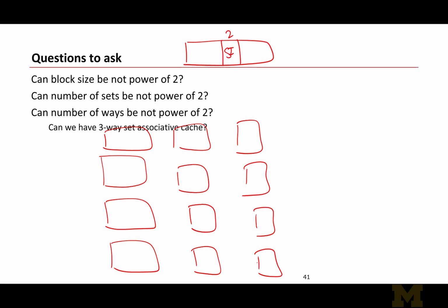So it is possible to define set associativity to be not a power of 2, as it doesn't really impact the way that we would configure the caches in terms of utilizing the number of bits and so forth. But oftentimes cache geometry matters when you lay out these structures in a processor chip, and symmetry helps.